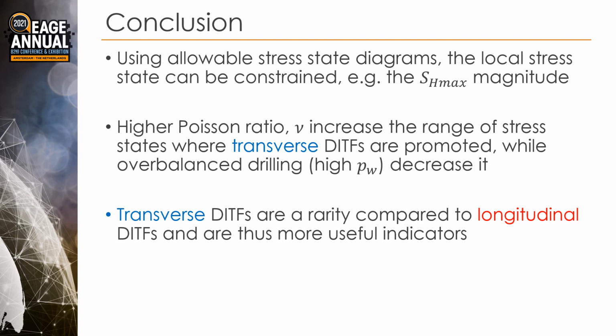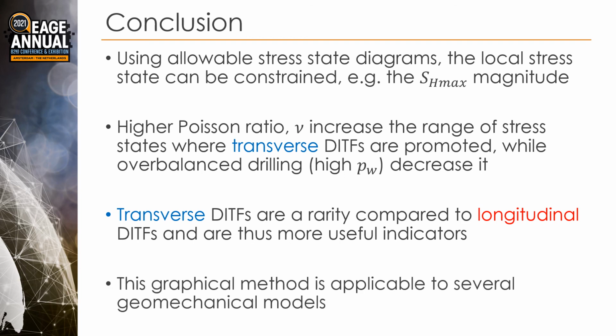Because transverse drilling-induced tensile fractures are rare compared to longitudinal, they are more useful as diagnostic tools. And the graphical method is applicable to any geomechanics model as long as you can create a closed form relationship for the axial and tangential stress on the wellbore radius, which is where the novelty of my work lies.